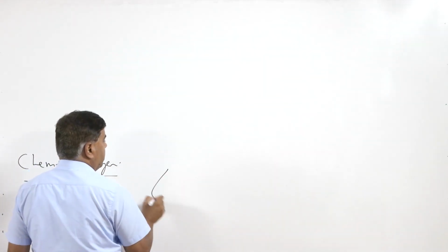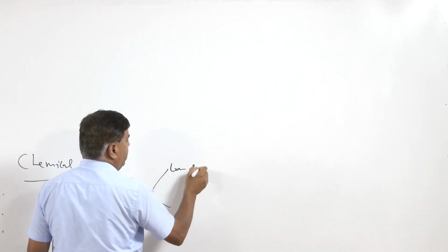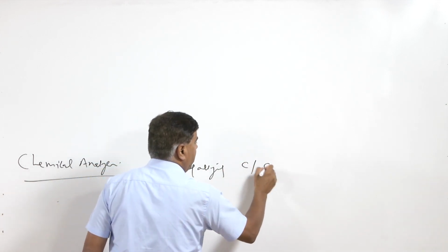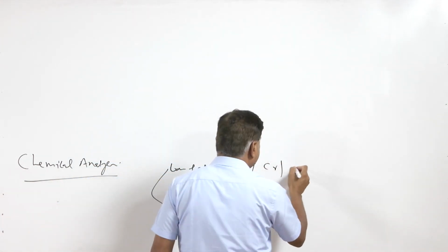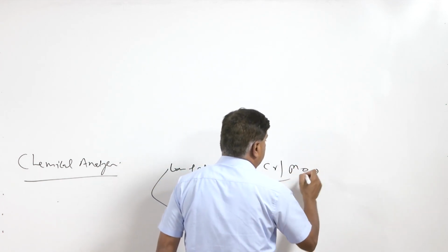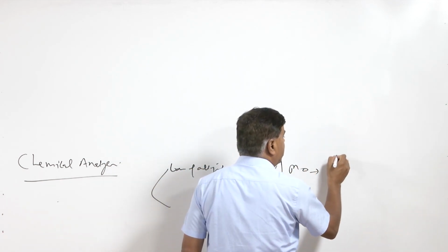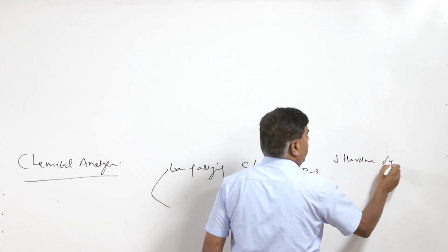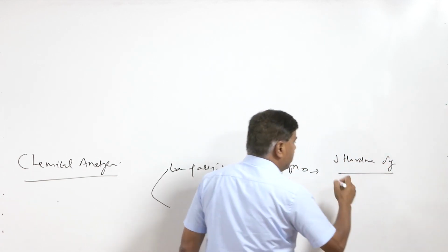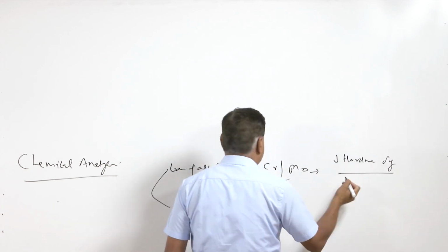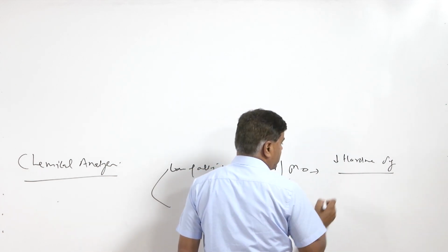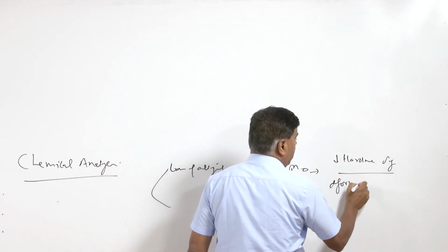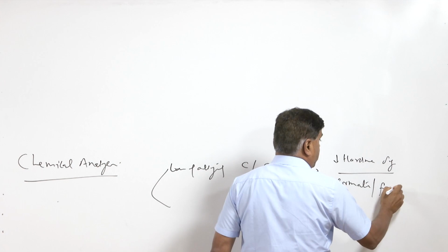One is, if it is the loss of alloying elements, for example loss of carbon or chromium or molybdenum from the surface, it will lead to a reduction in hardness and a reduction in the sigma y. This reduction in sigma y and hardness can lead to a loss of strength, and a loss of strength may lead to deformation or even fracture.